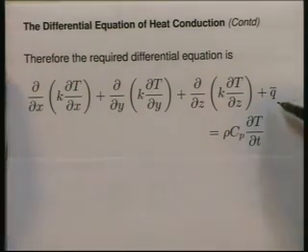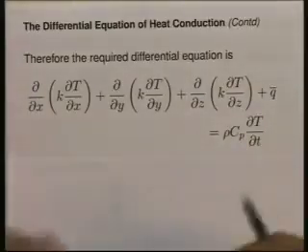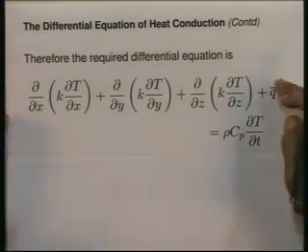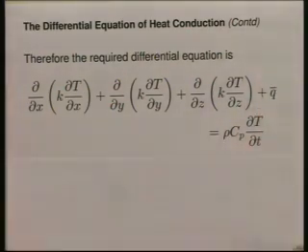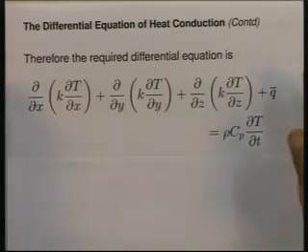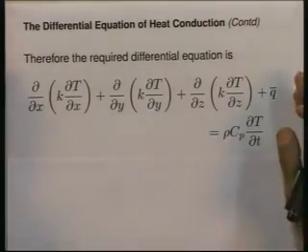This is a situation in which we have an isotropic material, we are working in a Cartesian coordinate system, all right. T can be a function of x, y, z and time, that is why we have a partial differential equation, and there may be heat generation q bar which may be varying or it may be constant, whatever it is, it will be some specified amount. So, this is the most general form of a differential equation that we have got.